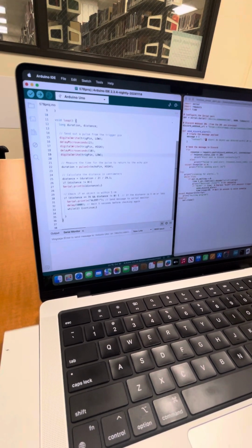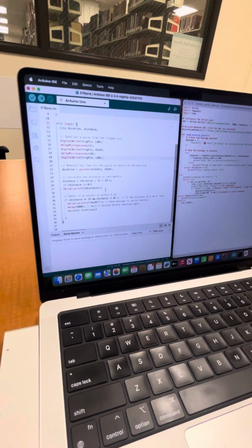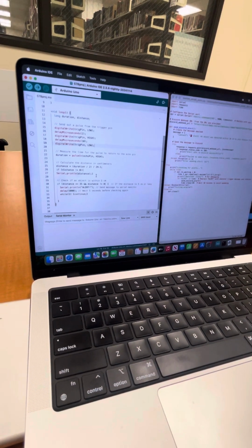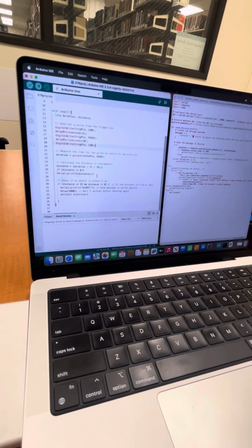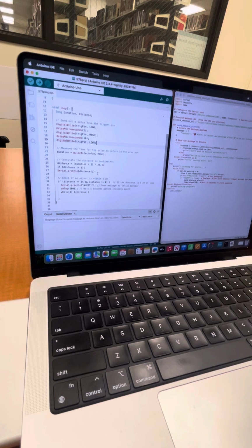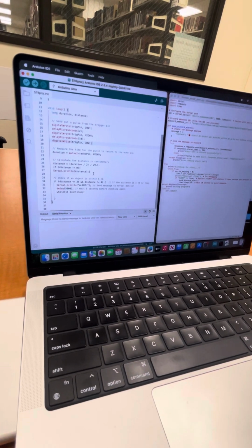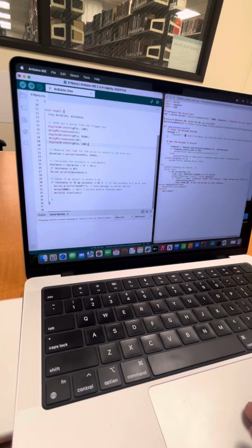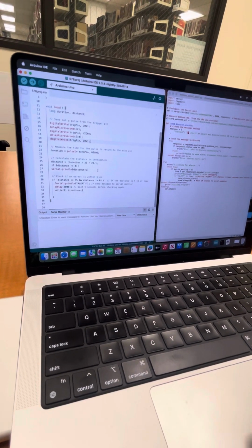And the reason why we put this if statement is because it sends out a high frequency sound. Sometimes waves can be disturbed by different things. For example, if things are too far, or if walls make the sound waves bounce back in weird or awkward angles. And sometimes because of that, it'll give no values, like 0. So this is kind of an error checking. So that's why you have this if statement.